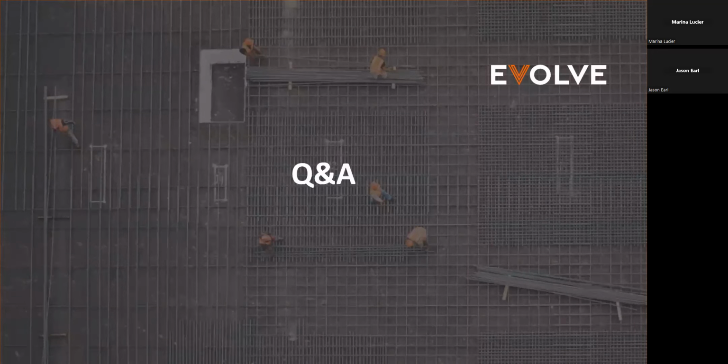All right, so the first one here from Brad says, I'm attempting to support the increased use of Dynamo in our company. What are best practices for maintaining package libraries? Do I need to keep separate libraries for each model year and separate scripts for nodes not available for each year? Build off the oldest year. Best practice for that. What I would say, if you're going to maintain packages, yes, I would probably manage packages by the year.